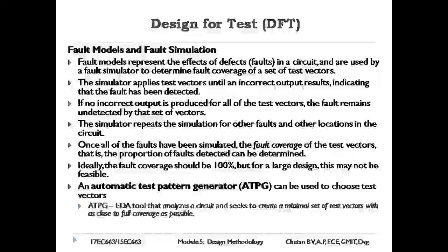The simulator applies test vectors until an incorrect output results, indicating the fault has been detected. If no incorrect output is produced for all of the test vectors, the fault remains undetected by the set of test vectors. The simulator repeats the simulation for other faults and other locations in the circuit.